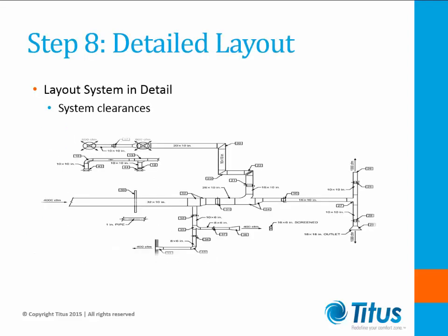Step 8. It's time for the detailed layout. Lay out the duct system in detail, or double line. Verify system clearances to plumbing systems, fire sprinklers, structural, and architectural features. When reviewing clearance, remember to account for bracing, duct connections, and insulation height.